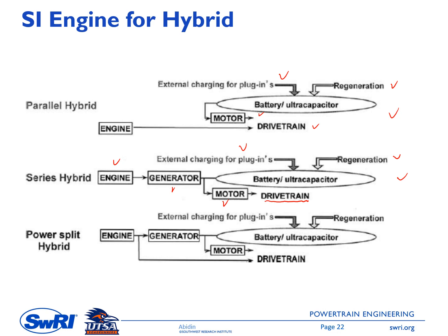At some points it can operate at the best optimum point, at other points it will have a very low efficiency. With this series hybrid, we can operate the engine at the optimum point because the engine operating condition is independent of the required power from the car. For sure, this series hybrid type is more expensive.